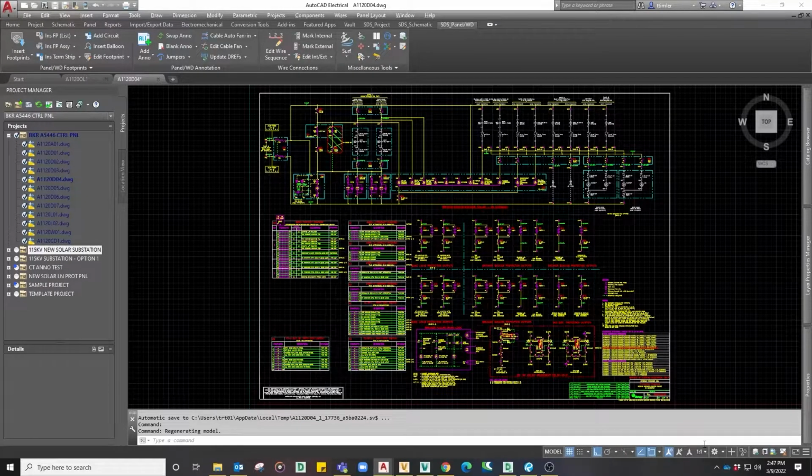This is a DC schematic in the breaker control panel that user 1 is working through. It contains smart device tables that will be annotated with the SDS table tool, pre-wired protection outputs located in the middle, and a breaker control circuit up at the top. Each of these pre-wired circuits represents a control function within the control panel that will be wired into adjacent protection and control panels during design. All panel subprojects have similar design elements.